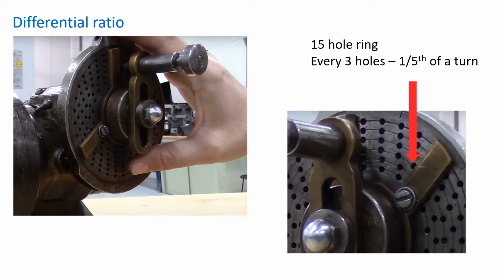You can see in this diagram I've set the sector arms to 3 holes so I can quickly index those positions. The main nut in the middle of the locking pin arm can be adjusted to allow the alignment of different hole PCDs on the hole plates.